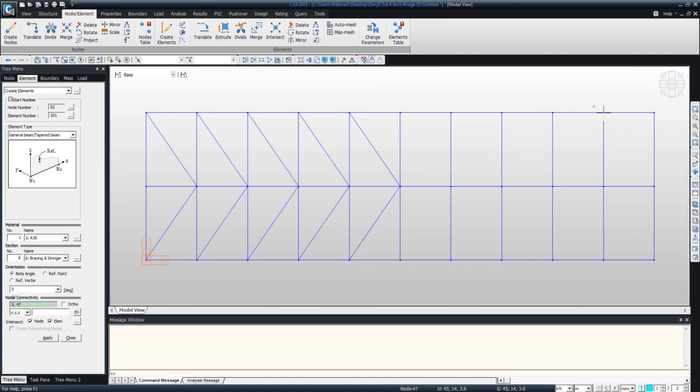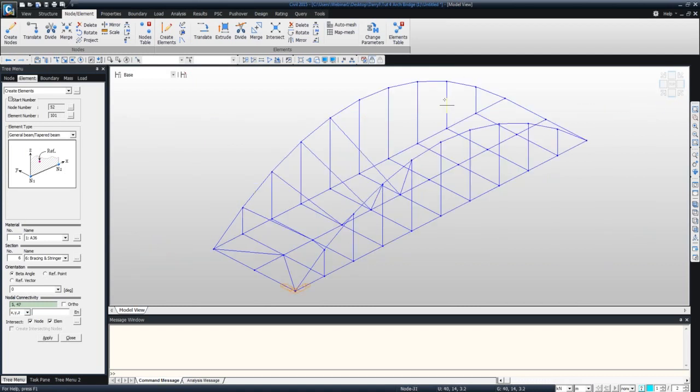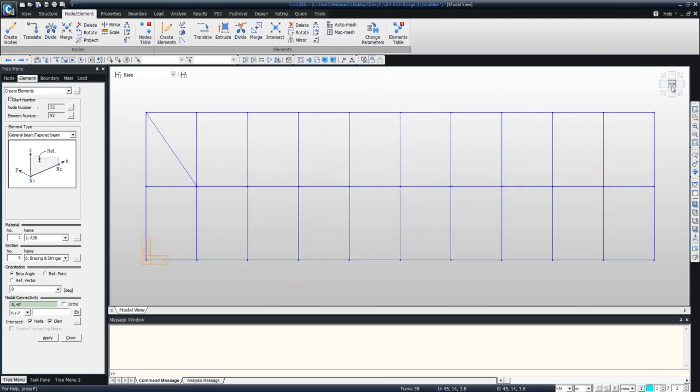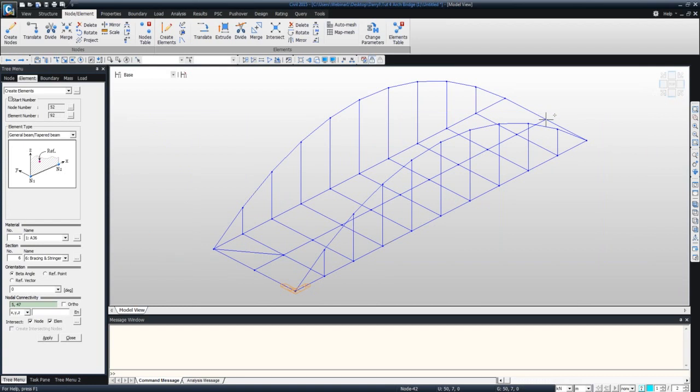Okay, so as you can see, I've created my first set of bracings. Oh, whoops. Okay, maybe I didn't. So let's actually undo that. A good rule of thumb: the reason I had an issue there was because with the overhead view, I accidentally selected that top node instead of that bottom node. So we can just make sure to select these bottom portions here.